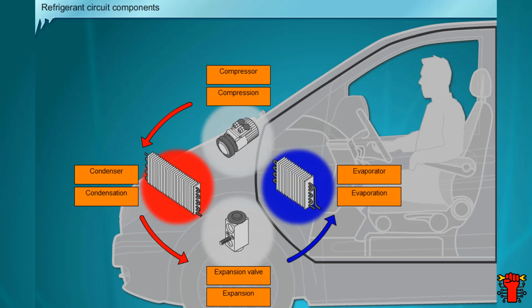The refrigerant in the evaporator reverts back to its gaseous state. The required latent heat of evaporation is provided by the surrounding air, which then cools the passenger compartment. The circuit is thus closed. In practice, an additional component is required. The fluid reservoir stores and provides the refrigerant. More information on the components is available in the subsequent chapters.